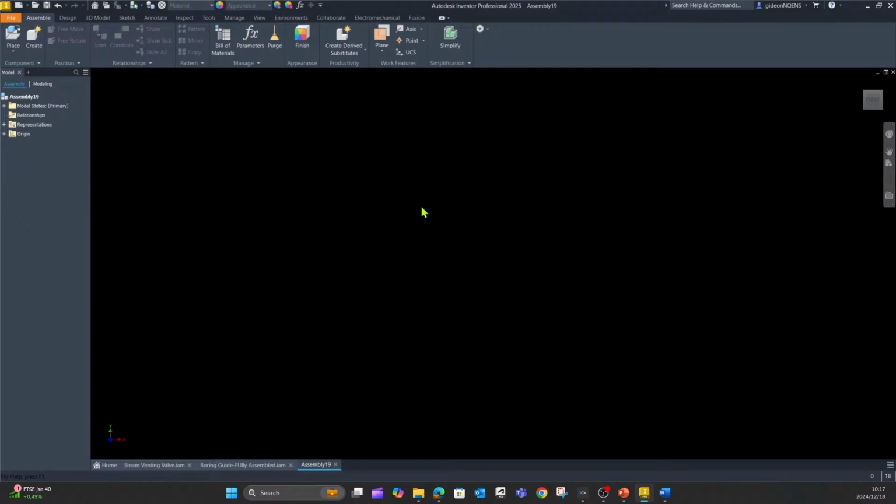Now once that is open, if you do remember on one of the slides, when it comes to the layout design, the first thing we do is open an assembly file. From there, the layout will create an IPT, and from the IPT we'll start creating all our individual blocks and then all our individual components or parts, depending on what is needed or required.